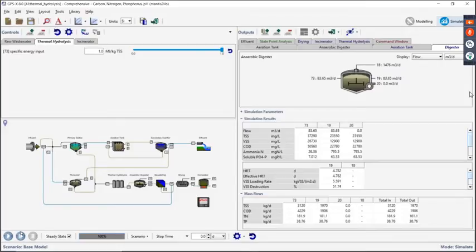Because theoretically now we've made it a little easier to digest, a little more readily biodegradable, and we can get a bit more methane production out of that. So this is coming to steady state here. And if we look at that same gas unit, it was 1478 before, and it's going to be about 1500 and something after this converges to steady state. So it's a nice way that you can use the model just to predict the fate of the solids that are coming around. And you can see that that breakdown of the COD makes it a little bit more favorable for digestion. It also releases back some ammonia and some phosphorus, though, too. So those will also go into their respective mass balances as well.